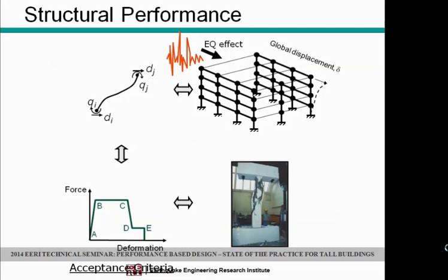So when we're doing a performance-based design, we build a model in our favorite software. We subject the model to simulations or recorded earthquake histories. We simulate the performance of the structural frame to those recorded histories.